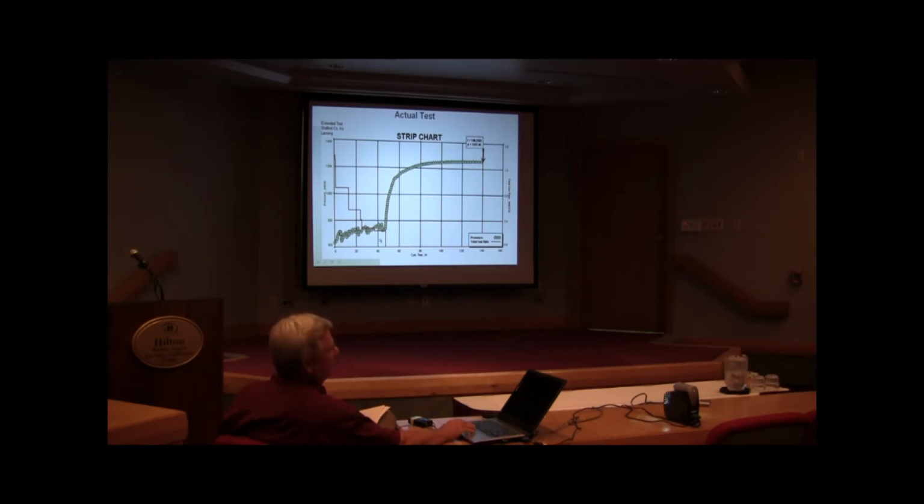Okay, so that was the design. Here's the actual test. In the actual test, we were not able to sustain the flow rate during that entire flow period. In fact, the flow rate dropped, but the pressure increased. That's a normal trend, in that you've got dropping rate and increasing pressure. We're showing a lot of liquid loading. That's what all this stuff is. We've got a few abnormalities in the curve through here, but we wound up at 1257 as our last shut-in pressure.